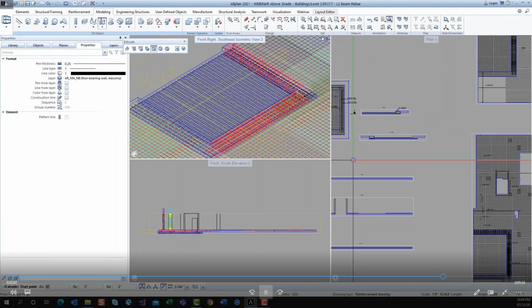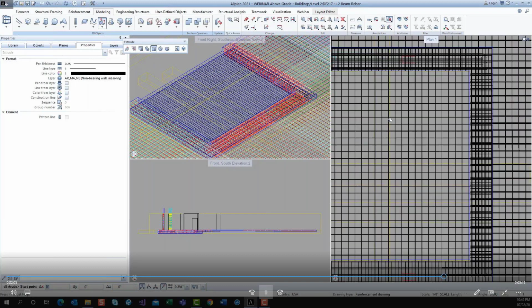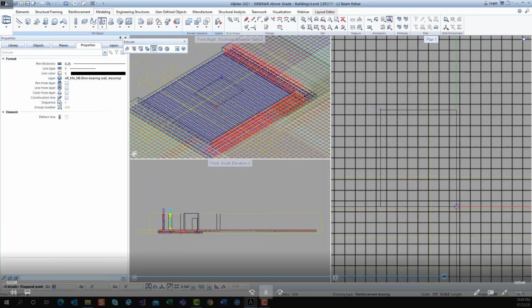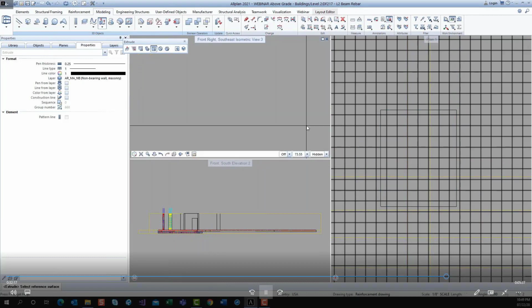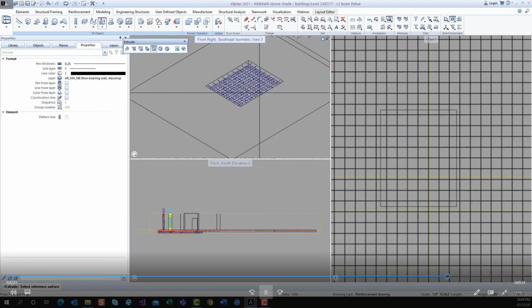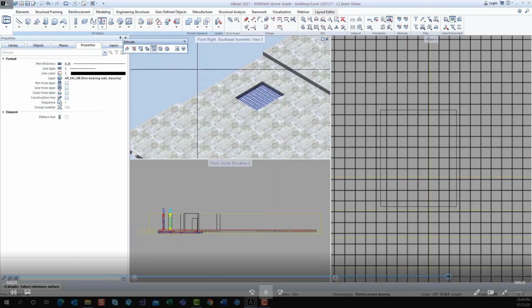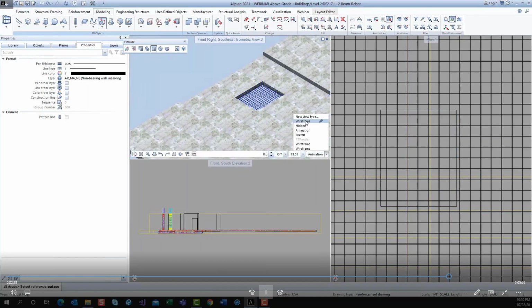So the first thing I'm doing here is creating that concrete opening. Create the concrete opening. I might have specifications at this point. I don't care. I just want a concrete opening. I do a negative value. I now have the opening in concrete. You can see my bars are going right through this opening. I don't want that to happen. So what I want to do is trim those bars, but I want to trim them all in one shot. And I want to define new ranges for each one of those.